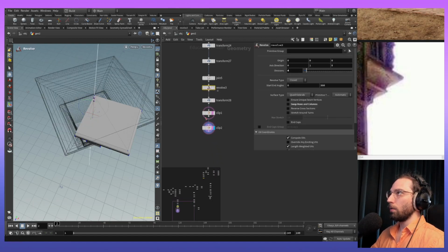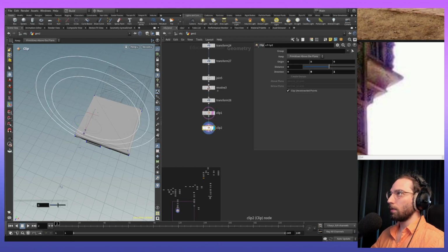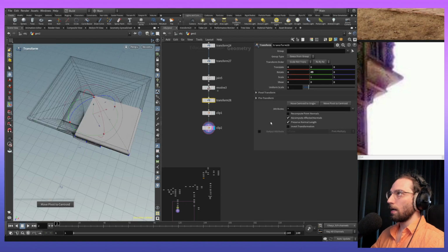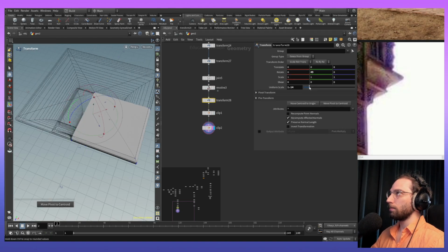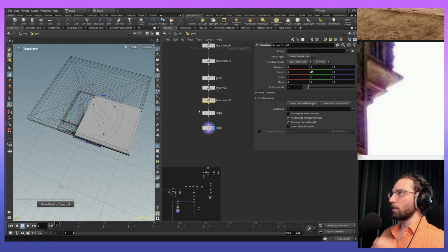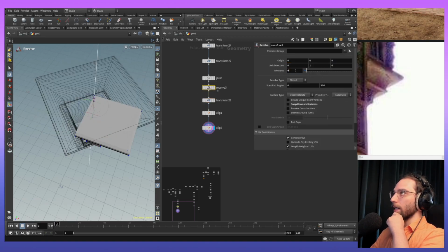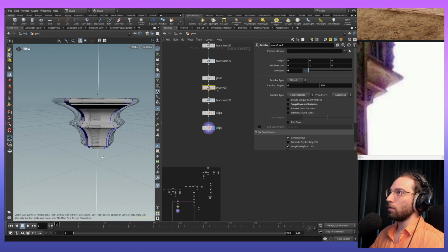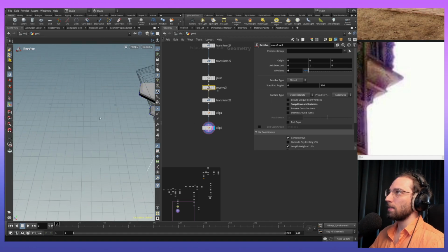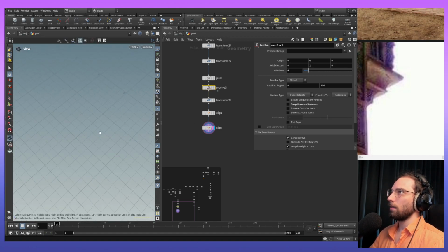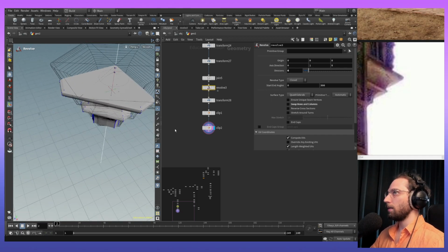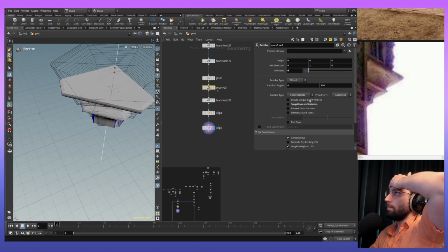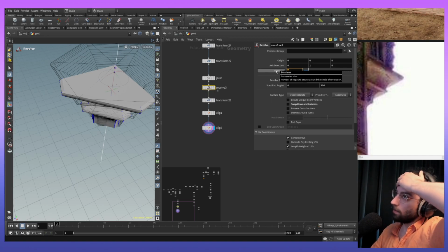And if we need more corners here, we go back to the revolve. All we need to do is remove the template here, put it here again. And now as we play with this, we should be able to play with the division of the revolve right there. And let's say we need 6 corners, and that should give us this result right there, which we will be able to use. Maybe not a 6 that we need here. Maybe we need a 7 in order to get a decent corner, a better one. Let's see, let's add a 7.